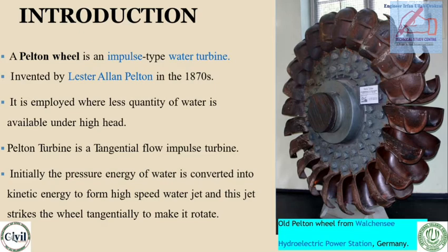First of all, we have a reservoir of water at some height. The water is arranged to move in a pipe called the penstock at very high speed to the lower altitude, where a turbine is set and the nozzle is set such that the high-speed jet of water strikes the buckets of the turbine and makes it rotate.